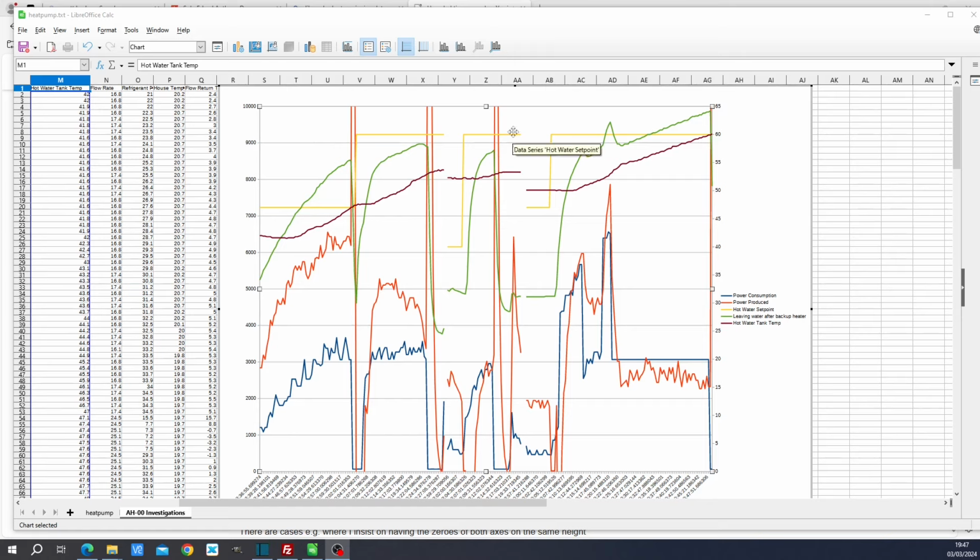After the second failure, as you can see, the coefficient of performance is really poor. We've got a good amount of power output here, over 4 kilowatts, and it ramps up to over 5 kilowatts in the first instance. Then it ramps down, so it's just on the compressor here, and then it ramps up again here, and that achieves your actual goal. Interestingly, you can see that the power input goes all the way back down to 3 kilowatts. Produced power is less than 3 kilowatts.